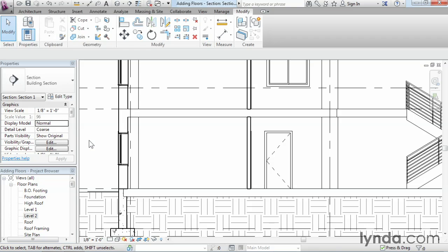So to create floor slabs in your model, it's a sketch-based object. Sketch-based objects are generated from 2-dimensional sketches, in this case drawn in a floor plan. You can generate that sketch from the surrounding walls, or you can draw it line by line. When you complete the sketch, Revit will create the 3D geometry that's needed for your floor slab.